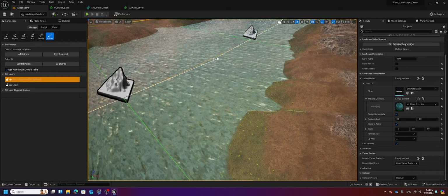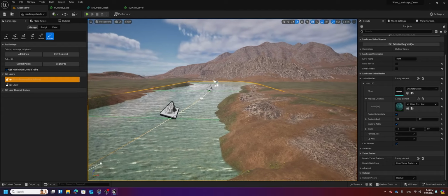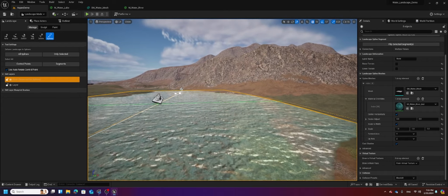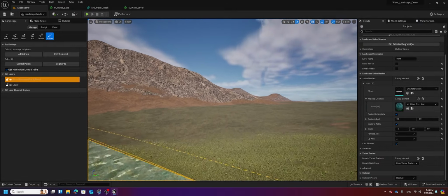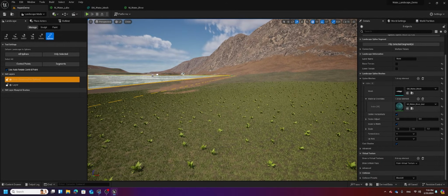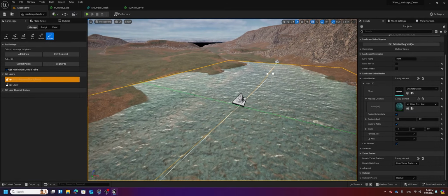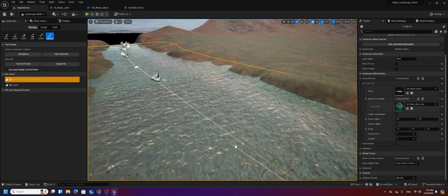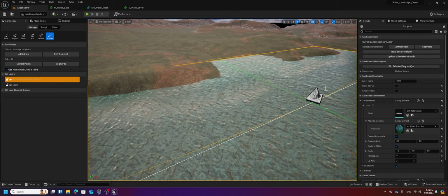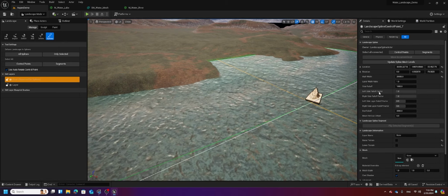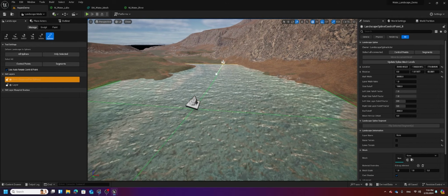And it is going the wrong direction. Or is this down? I cannot remember. I think that might be down. So that's the down direction. So it's flowing that direction. And yeah. So again, hovering above the ground here, I have to kind of fix my terrain and fix these positions, and you can grab them individually and change them. You can change the width separately. You don't have to make them all the same. Here on the control points, you can select individual control points, and you can change the width of individual control points. You can move individual ones up and down.